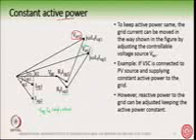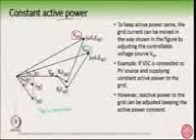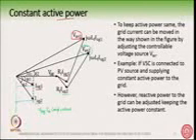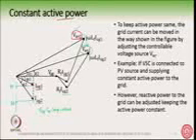But what happens is the reactive power. If you see, these are the two reactive powers, Q1 and Q2. This is because of the quadrature component of current with respect to the voltage VAG. This is changing the reactive power. So by shifting the VAN to VAN2, we have kept the active power constant into the grid, but we have changed the reactive power supplied by the voltage source converter into the grid. That is what we have done by moving the phasor VAN1 to VAN2.